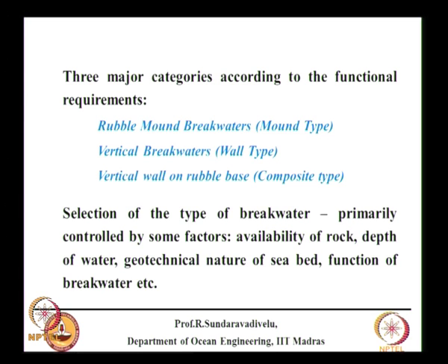Certain condition means not the design of the structure, we know what is the air gap that is required. Air gap means water level plus the wave height, then 1 meter air gap. For that case wave height we take 1 in 1000 year, only for the air gap, because if the wave is hitting the bottom of the deck, the wave force will be enormous, we want to avoid that.